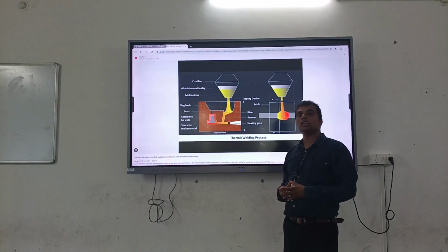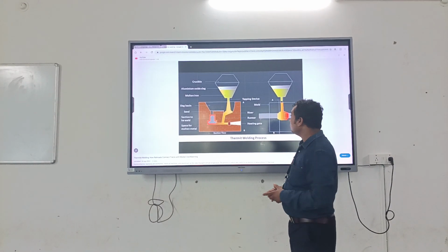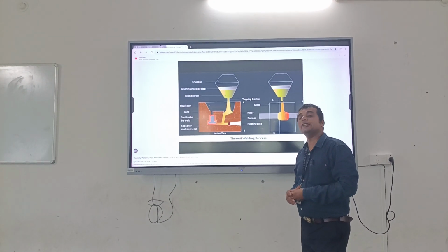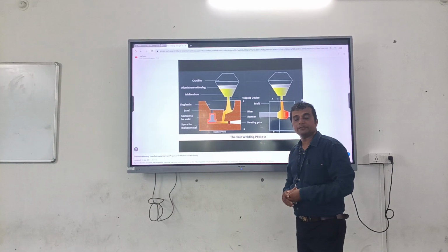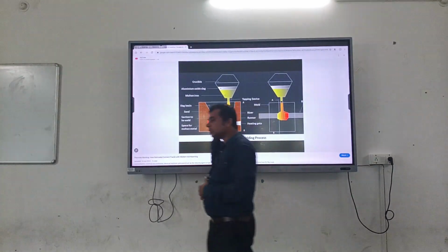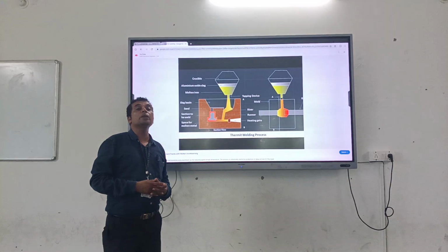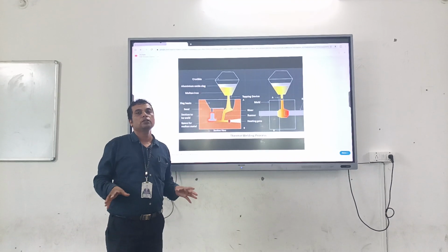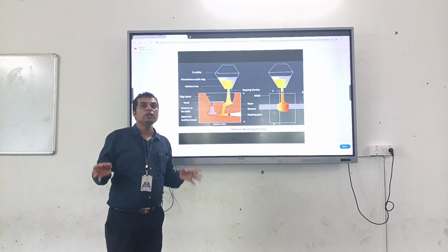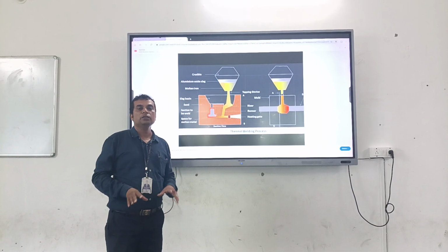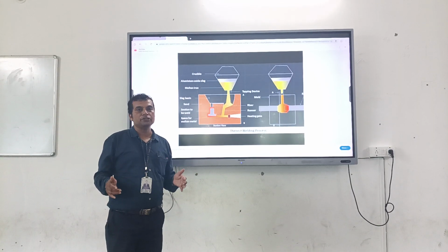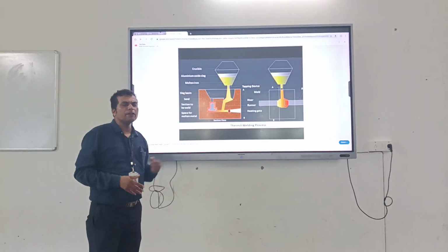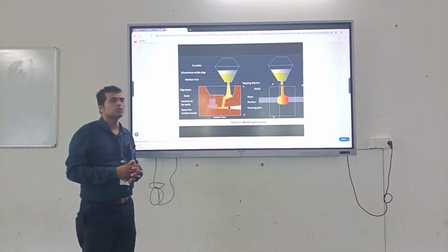We can also perform welding in this section. This is a welding of non-pressure type thermit welding. Non-pressure type thermit welding is where we do not apply any pressure in between the two metal parts, or broken metal parts, we can join them without applying pressure on two metal plates or two metal rods or broken parts. Okay. So what are the advantages of the thermit welding process?